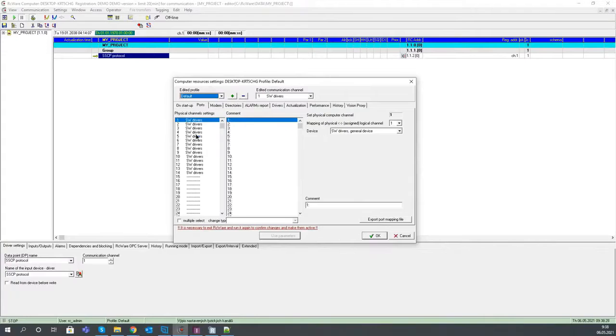And some of them may be configured as software drivers. So this is what we need for the Merbon PLC to connect to, and for the soft PLCs as well. Other options are also a bit old-fashioned, like serial line for direct connection over a RS-232 port, which is not used anymore, modem for a dial-up connection, and the network adapter, which is something we don't want to know anything about. So the result is that the software drivers general device, that's what's necessary to do here.